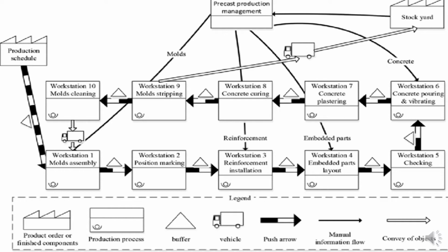Storage of high-quality units in works area. Storage of precast concrete. The finished precast components are stacked on clean battens or plastic pads positioned to suit the design of the component. Care is taken to keep the stacks vertical and to ensure that battens are placed directly above one another within the stack.